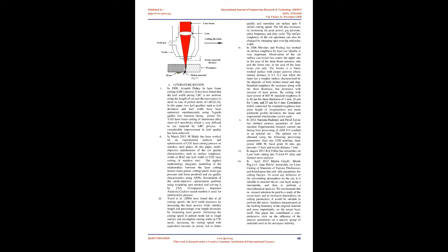This distance influences the flow patterns in the gas, which have a direct bearing on the cutting performance and cut quality. Large variations in pressure can occur if the standoff distance is greater than about 1 mm. A standoff distance smaller than the nozzle diameter is recommended because larger standoff distances result in turbulence and large pressure changes in the gap between the nozzle and workpiece. With a short standoff distance, the kerf acts as a nozzle and the nozzle geometry is not so critical.